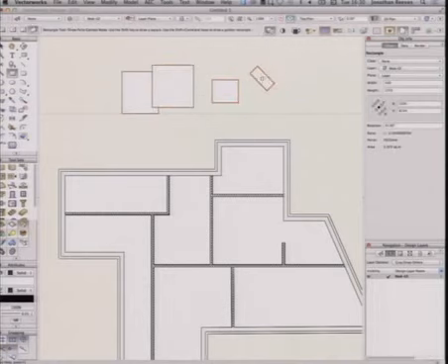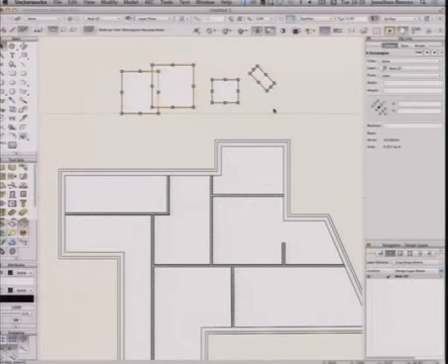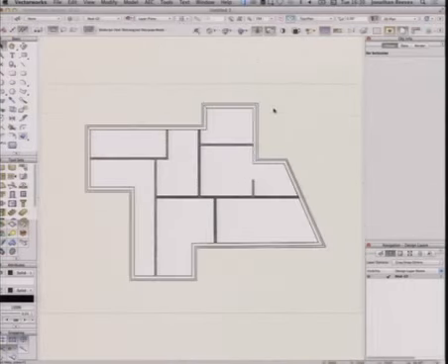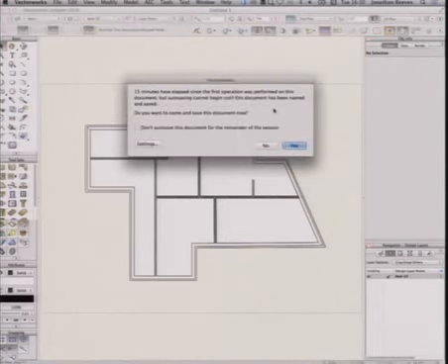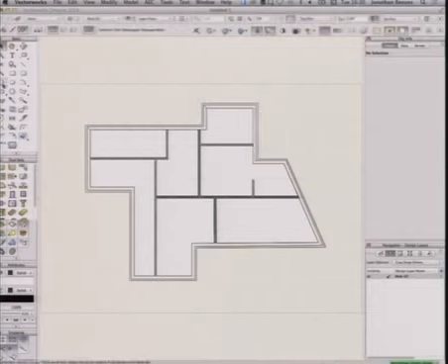Obviously you can't see me using the keyboard, but you can see that I'm not clicking on tools to access any of those drawing tools. So that's my definitely first empowering tip is edit your workspace to make the shortcuts easy. Secondly, learn those easy shortcuts. And thirdly, remember the Vectorworks mantra, if you like, tool, mode, maneuver. So what that means is you get your tool, you go for your mode, get the right mode, then you do the maneuver. And the trick I find with learners is people who are starting out, they always forget the mode and they don't look at what they're doing. So, keep an eye on this.